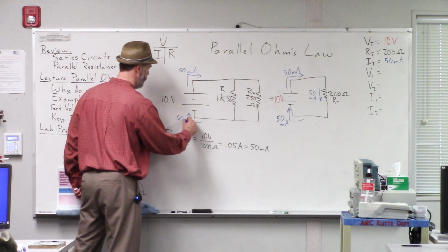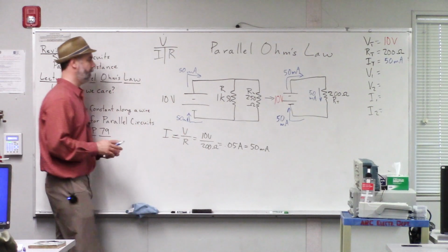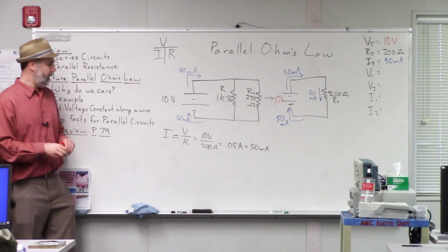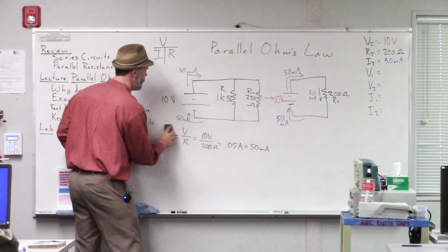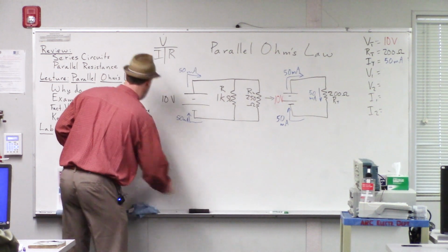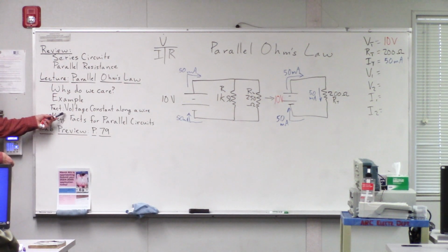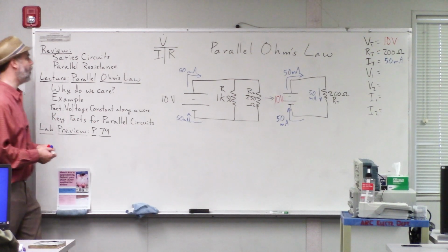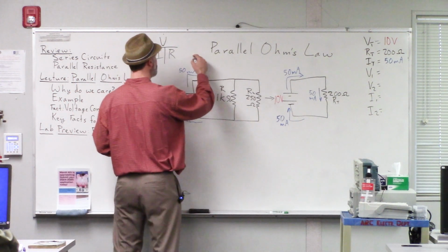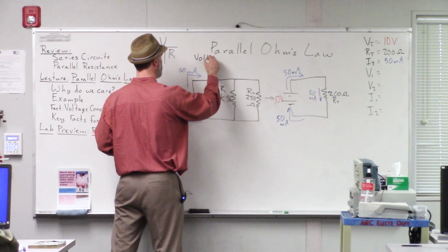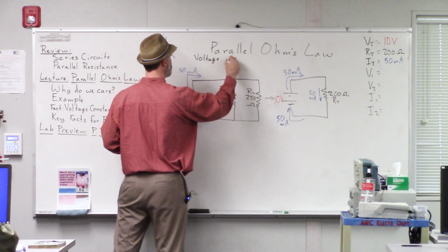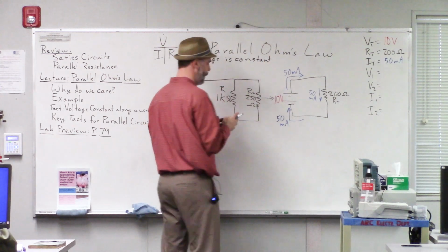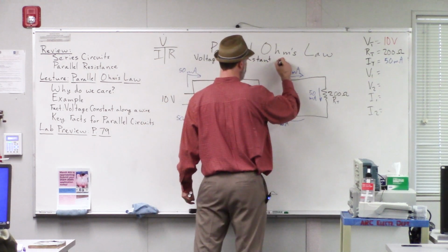The voltage of the branches? Sure. Yeah, so we can look at the voltages for these resistors. So this is where this key fact comes into play that's really important. In any circuit that we're looking at, voltage is constant along a wire. That's a little bit of an approximation, but it works.